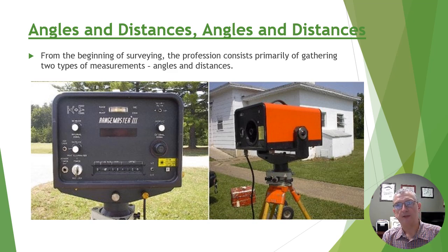And obviously I'm not talking about topographic surveys, benchmarks, and establishing grades for railroads and early highways. I mean for property surveys. Angles and distances. Angles and distances may have been measured by a compass, may have been measured by an instrument. Distances may have been measured by an Egyptian rope, a gunner's chain, or calibrated steel tape. We're looking now at the modern era.